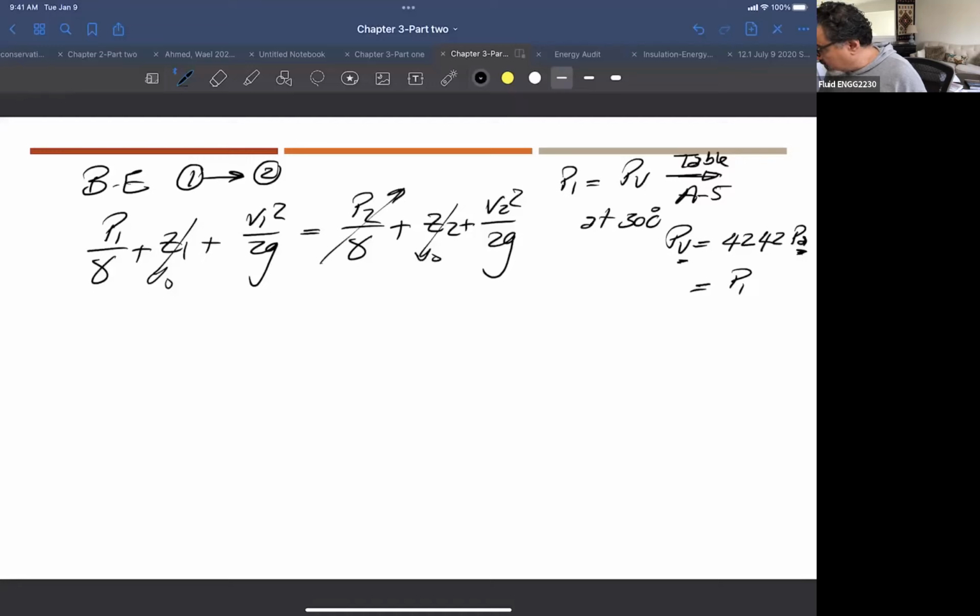That's why I'm asking this question, I just need to find out this vapor pressure. Did anybody find it? It doesn't say absolute, right? So which means gauge, right? So this is basically gauge. I'm just trying to check because sometimes tables are listed in absolute, which means in this case you have to take the atmospheric pressure as 100 kilopascal and so on, right?